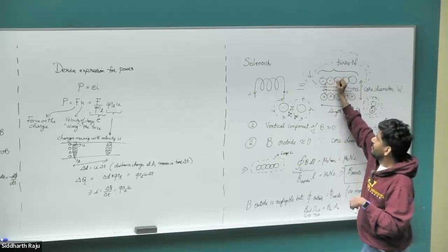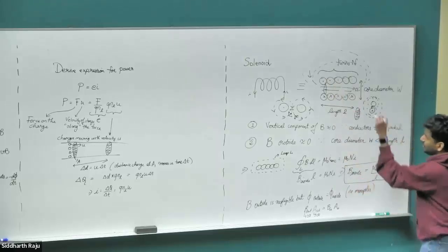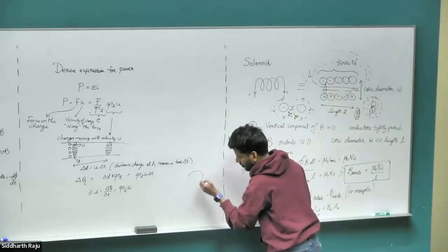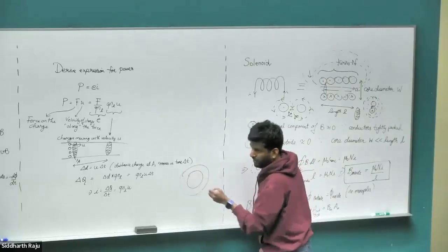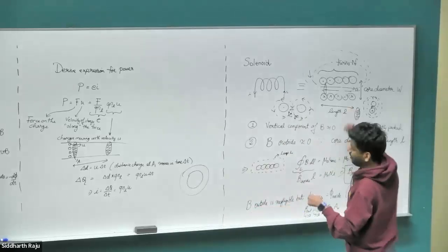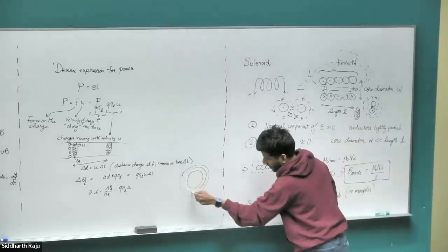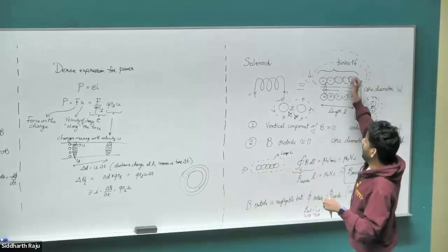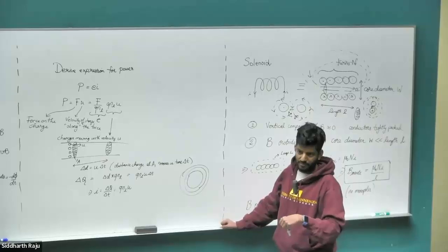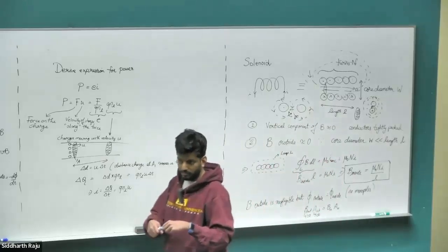But in this particular structure, the way I've drawn it is an open structure. In reality, you would have something like a closed toroid over which you would wind these windings, so that this pathway closes through the iron core and not through an air gap like this. This is how you would end up reducing the leakage component that we have. Any other questions?